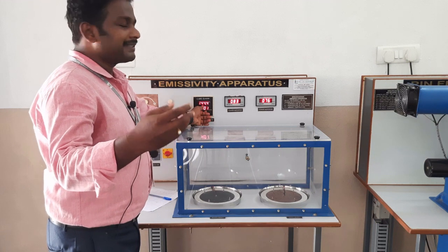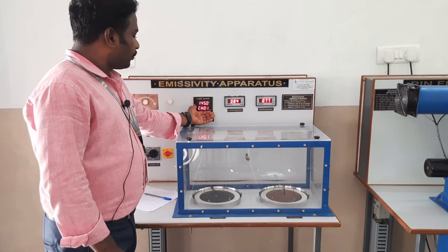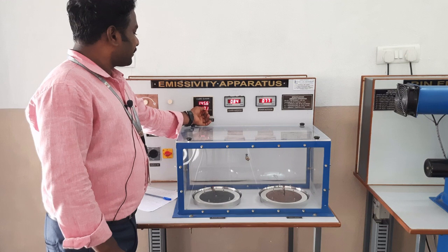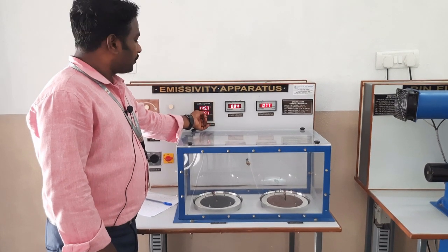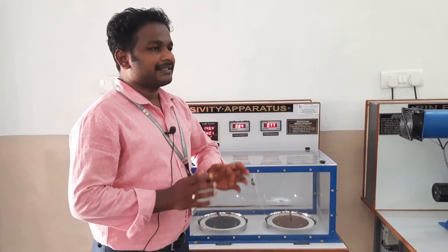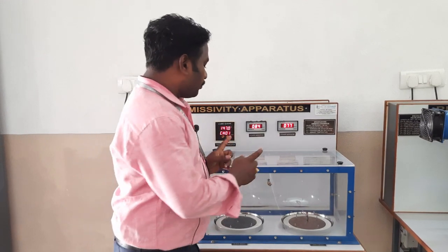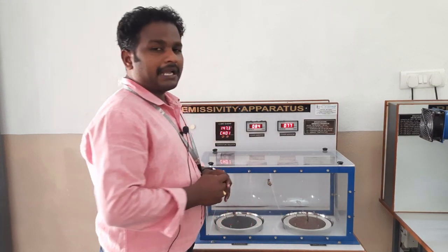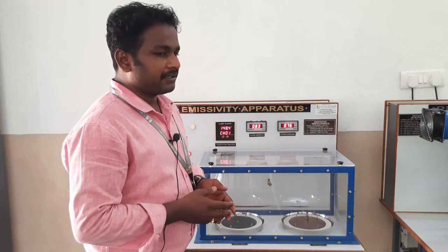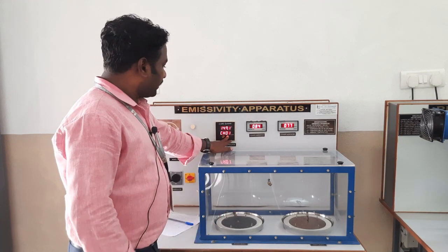The temperature is varying second to second because it is in an unsteady state. So you have to wait until the steady state condition is reached. When it reaches steady state, the temperature does not change with time. So you have to wait until the temperature reading stops changing. And one thing you have to keep in mind while calculating the emissivity: the two bodies, grey body and black body, must have the same temperature, and if you are not maintaining the same temperature, it is not possible to compare the emissivity.